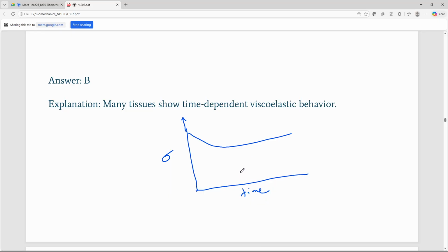That's with respect to time, how the applied stress behaves. I already told you the stress is the internal resistance to the applied load. So, if the same load is applied, then with respect to time, what will happen to the internal resistance? That is what time dependent behavior is. This is a typical graph for a viscoelastic material. This is stress versus time, and strain versus time will be something like this.